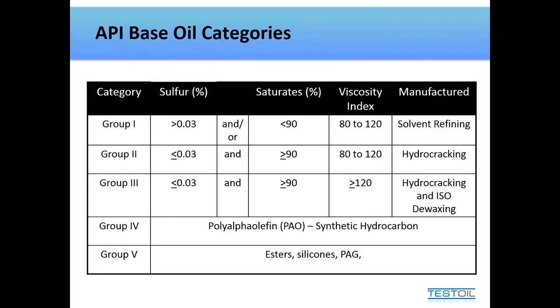For instance, if you live in Alaska or the North Pole or something, you're at negative 20, 30 degrees at times. Say that same equipment may see temperatures above 130 when it's run up. An oil's ability to maintain a consistent viscosity and not vary too much between those two temperature extremes is your viscosity index.